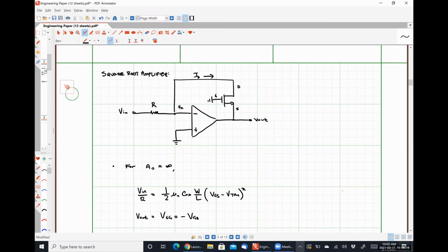It's instantly going to go into cutoff whenever our input voltage goes negative, which breaks our feedback loop. And again, we have an open loop amplifier where a negative input voltage corresponds to an output voltage of VCC plus, or a positive power supply. Does that make sense? So it seems like the current should just flow the other direction, but we no longer have our diode connected transistor, which means we're no longer guaranteed saturation operation.